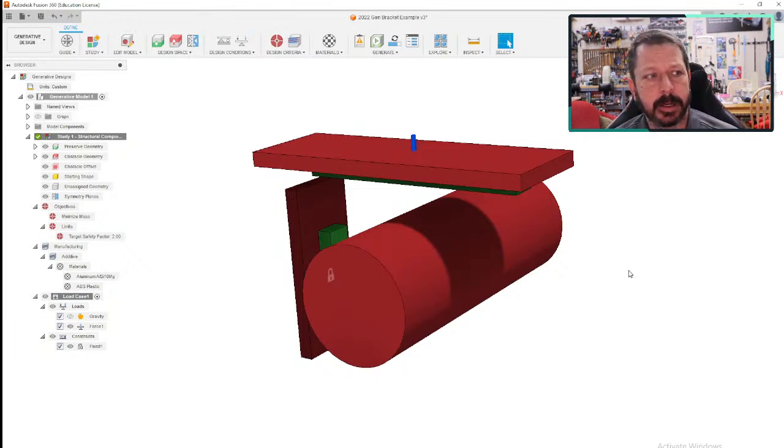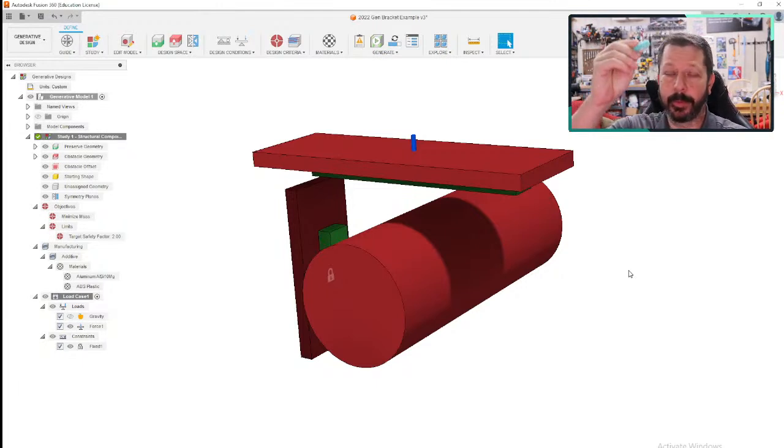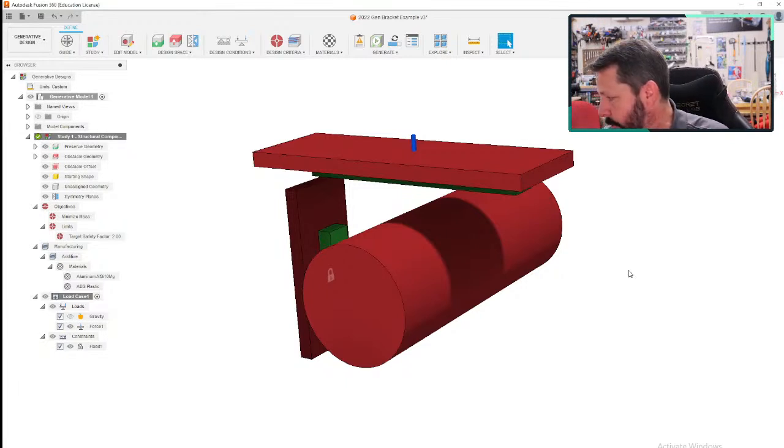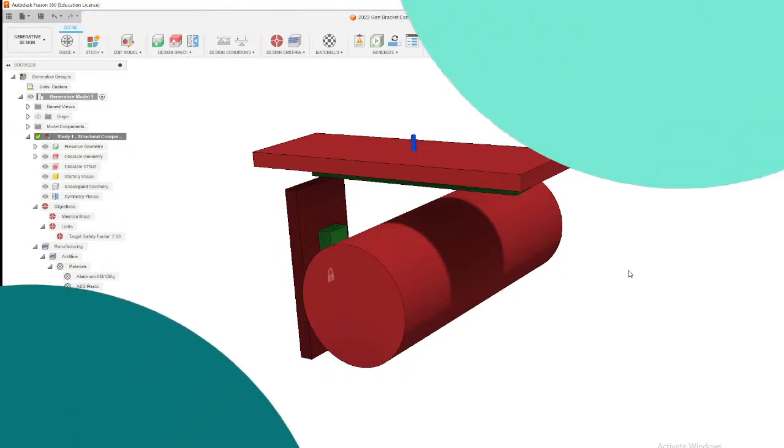You do have to be considerate that resin printing is typically pretty brittle at the consumer level until you add in some of the tough resin or a little flexible resin or something like that. The standard resin is pretty brittle on its own. These little parts are not going to break, but if they had tiny details, let's see if we can get close to some of their details so you can see what we did print.